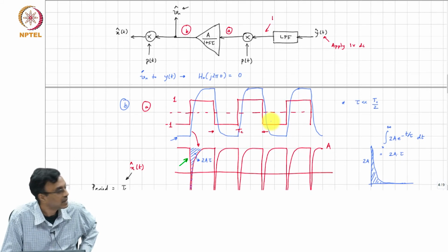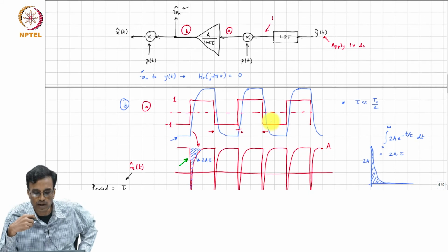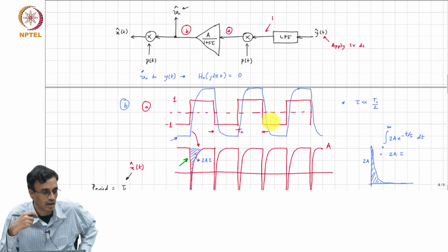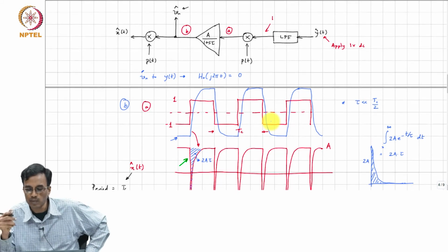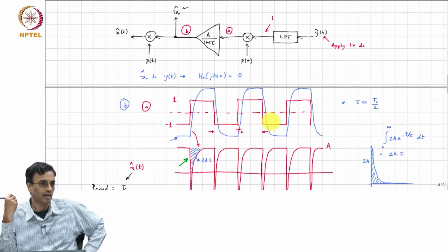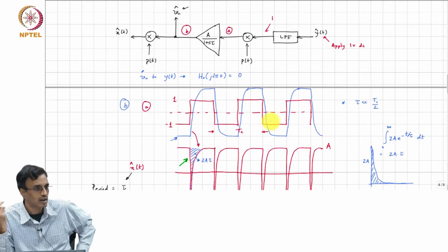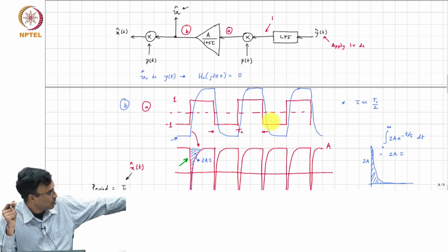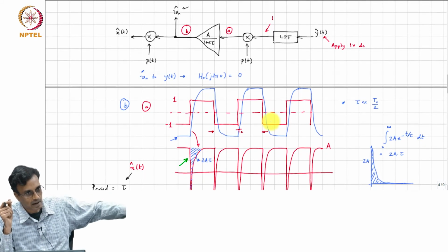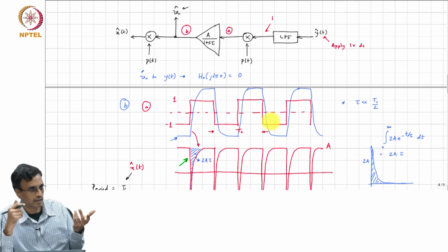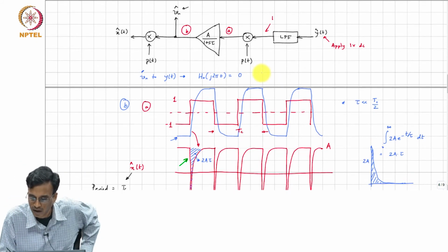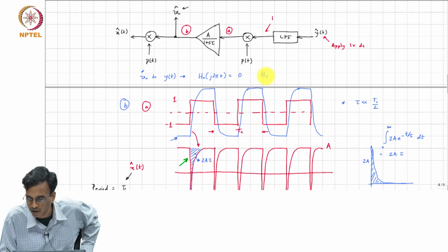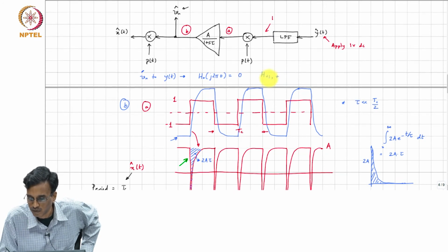It has a period of Tc, which basically means the Fourier series has components at multiples of FC. However, since the duty cycle of the square wave is 50%, it will only have odd harmonics, right. So, H plus minus 1, plus minus 3, plus minus 5, etc. are non-zero,